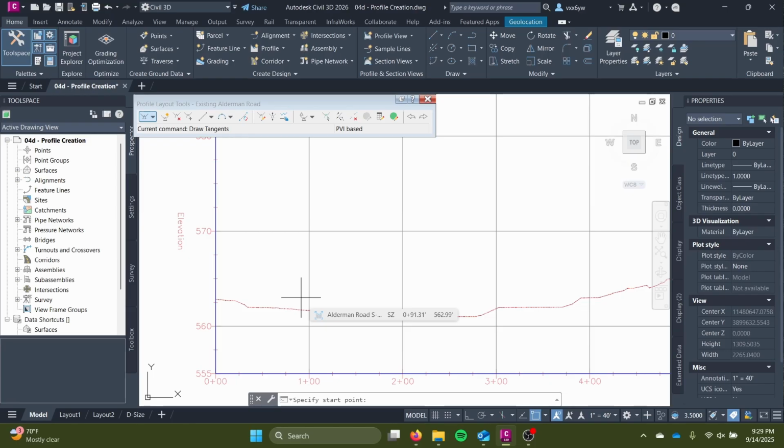The other thing to keep in mind is that you want your road to pretty closely match the existing surface elevation. Anything a lot higher or a lot lower means more ground that you have to dig out, a tunnel you have to build, a bridge you have to build, dirt you have to fill in, and all that adds cost and time and complexity to your project. Now, I know here we're modeling an existing road, but we can imagine that the designers did a similar thing when they were designing their road.